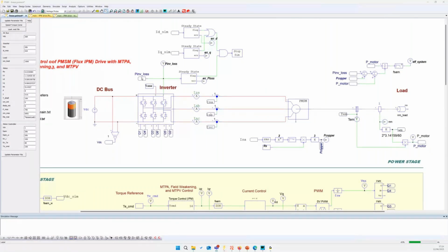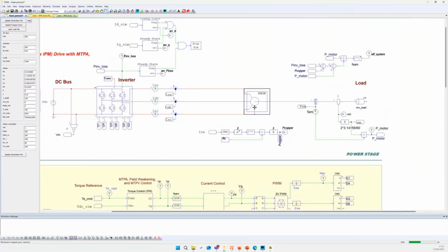And when it comes to the linear model, we can only calculate the copper losses because there is no 1D tool that has information when it comes to the core losses, because that involves geometry and material. You can get the core losses inside PSIM if you include the Flux models. So if you have your motor designed in Flux, you can export it, use it inside PSIM, and this will include the core losses. And this is, in my opinion, very major because we are enabling these insights from the FEA tool inside the 1D simulation.